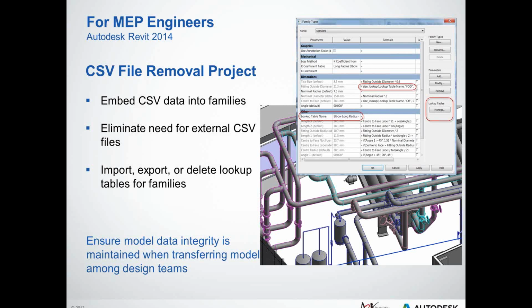In 2014, we can now nest the lookup table inside the component so that when that component gets shipped to somebody, there isn't a missing file. It's actually embedded inside the family, which is good. And you can see on the right-hand side here that we now have a Lookup Tables Manage button in order to facilitate, I guess, a similar process to what we had in 2013, but now directly inside of the family itself.